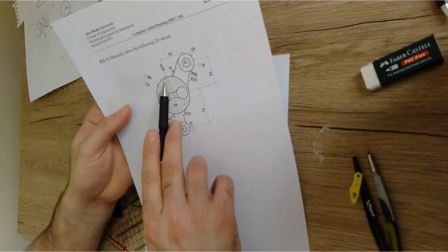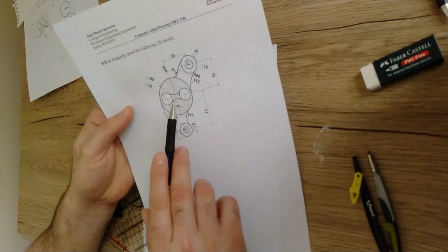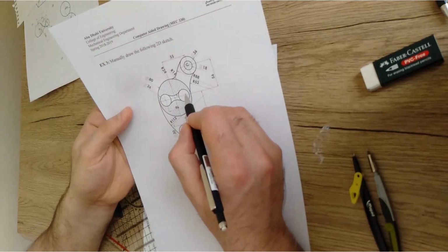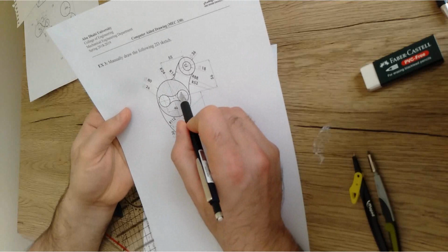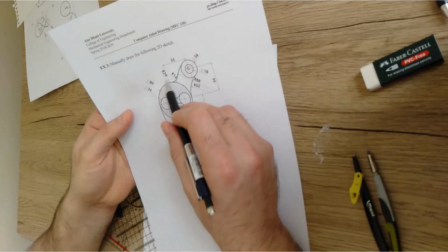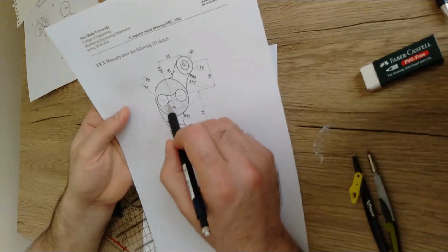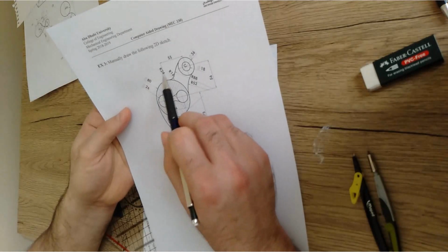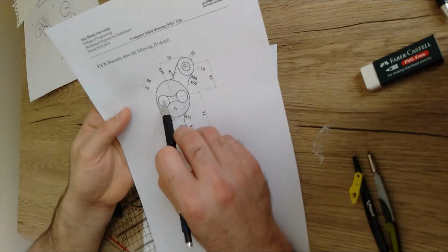And if I ask you to move from this center to the center of this curve, are we going to go over the tangent point? Yes, we're going to go over the tangent point, which is this one. It means that we have to add the radii. So we're going to have 13, which is the radius of this circle, plus the 24, which gives 37 in total, right?